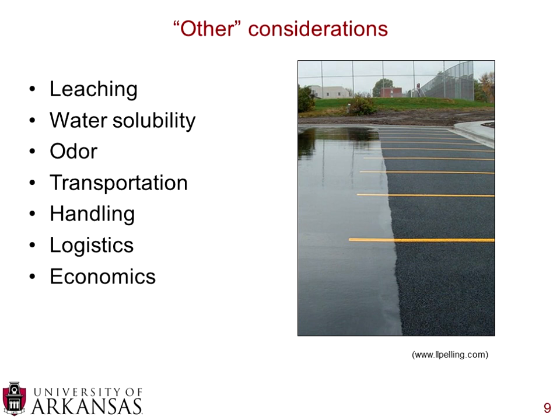Obviously, transportation and handling of the material is absolutely critical. If your asphalt plants are hundreds of miles from the source of this material, that won't be able to work out very well. And if it's not able to transport in a convenient form, you'll also have problems with that. When you get to the plant, there's always issues. Are you going to take these biobinders and blend them at the refinery? You'll need special tanks for those. Are you just going to simply fill up a truck and hope it blends as you drive down the road? Or is a plant going to designate a tank that's able to have a mixer to mix the biobinder in with the asphalt cement? So lots of different handling questions.